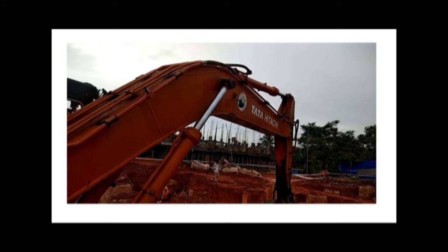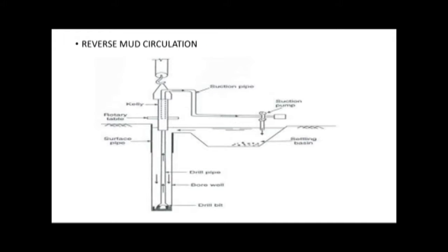Also, the water has to be properly drawn out from the site, because otherwise it may create clogging or unsatisfactory site conditions. So proper trenches are to be excavated for that, and a proper direction is to be provided. A path is to be laid down for the water, so that it could easily move through that path.